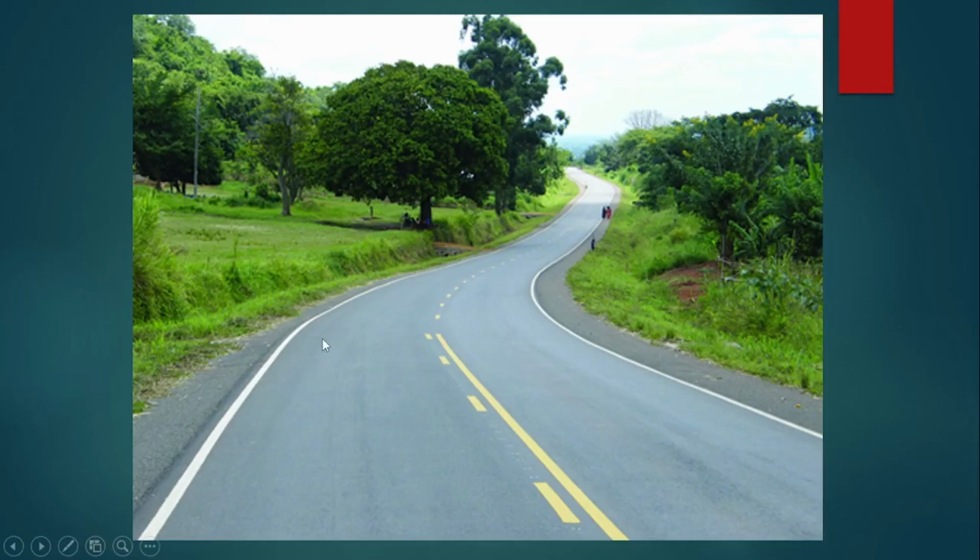We can look at an image of a road here. Here we have the center line of the road, which is represented by the center line alignment that we have created already. So we are going to offset this alignment on either side so that we're going to design a two-lane road. We are going to offset the center line on both sides, but you can see that at the edge of this lane, we shall have the shoulder on this side and then on the other side of the road. For now, let's first stop at that.